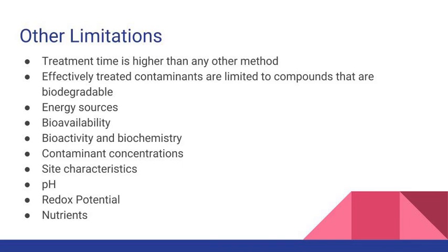The pH affects the solubility and the biological availability of the nutrients, metals, and other constituents for optimal biological growth. The pH should remain within the tolerance range for a target microorganism. Biological remediation processes prefer pHs between 6 and 8. Redox potential, which is another site characteristic, and the oxygen content determine oxidizing or reducing conditions. Redox potential is influenced by the presence of electron acceptors such as nitrate, manganese oxides, iron oxides, and sulfates.